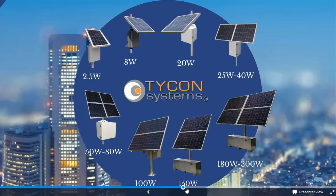Or maybe you're doing an irrigation pump. As you can see, the top left is our 15 watt panel with a DC enclosure. It has a 9 amp hour battery bank. That'll give you 2.5 watts of continuous power with 6 hours of peak sunlight. Well, that's not a lot. This device is designed for small applications. Maybe you're powering an irrigation pump and only need to run it 30 minutes a day, because obviously you're going to have much higher than 2.5 watts draw.